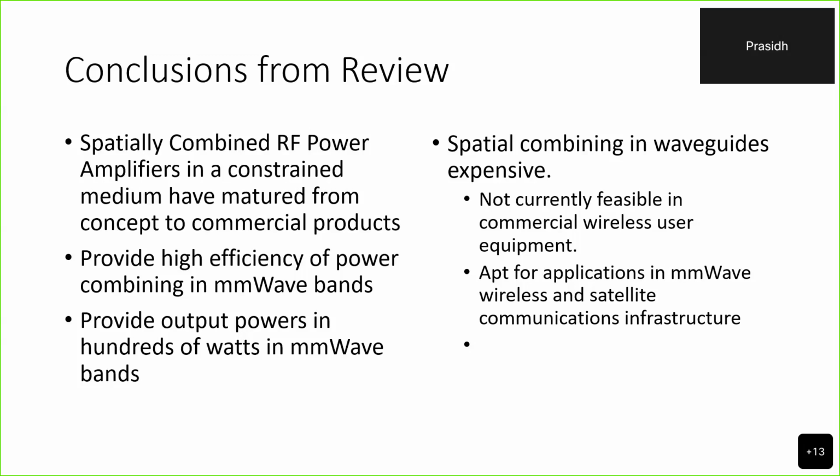They also provide output powers in the range of hundreds of watts, primarily due to the high power handling capability of waveguides. But we also have a few demerits here. It's currently not feasible for commercial user equipment because these are going to be highly expensive, as waveguides involve quite an amount of machining to get the surface roughness very low. That is mainly to mitigate field perturbation and conductive losses. It is however apt for applications in millimeter wave infrastructure, like base stations or satellite communications.